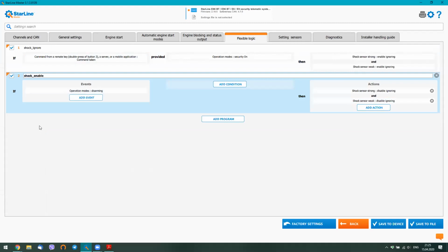The ES1 sensor has 3 wires. Red is positive, connected to somewhere positive 12 volts. Black is negative, you can connect it to the ground. And the green one is the signal wire. It's negative. So when you touch the ES1 sensor, it's a capacity sensor. When you touch it, it enables the green wire. It gives a negative signal to the green wire, a ground signal. So while you touch it, while you hold it, the green wire is negative.